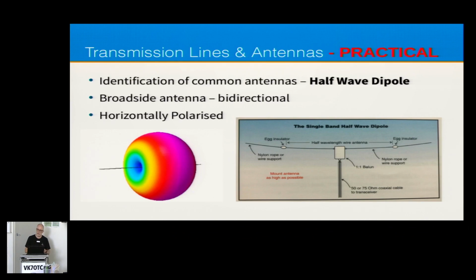Why don't people use circular polarisation? Different polarisation type altogether. For satellites, we use circular polarisation, well and truly. Wouldn't that give you better point-to-point contact if you don't know if you're going over water or not? Yeah, spot on. As signals travel through the atmosphere, they change their polarisation. As they bounce off of things, they change their polarisation. And so, that's why a lot of antennas you'll see at 45 degrees, because it's halfway between vertical and horizontal. So you don't actually get as much loss, but it's more likely going to pick up enough signal for you to be able to receive the signal. So all sorts of things.